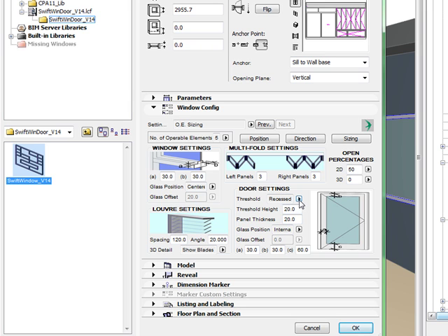For the door settings you can also define a threshold type of standard or recessed. When you define standard, you can then nominate the threshold height. Both the Swift window and the Swift door are completely identical parts. One is simply accessed through the door tool and the other accessed through the window tool, allowing you to choose whichever tool you like to configure your wall openings.